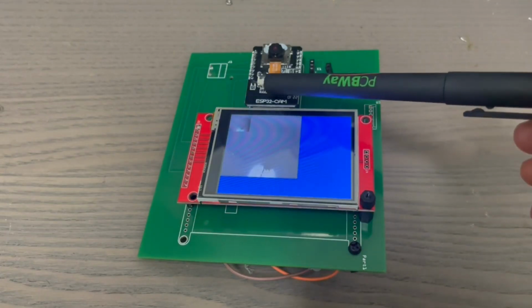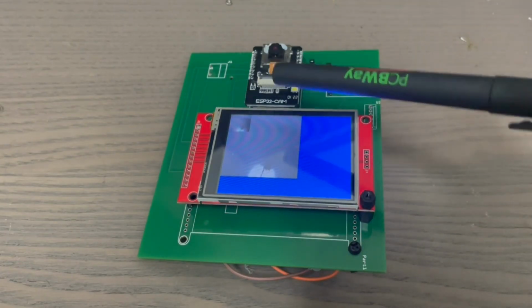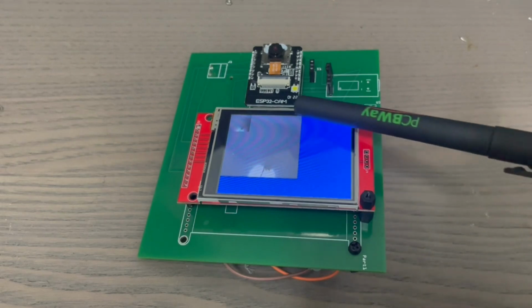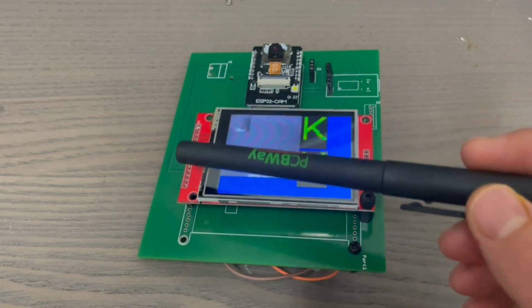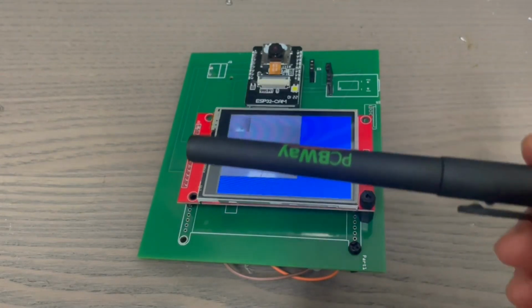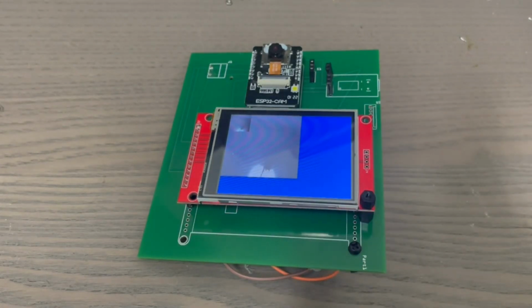I've uploaded the code to the ESP32, and the hand needs to be positioned fairly precisely in front of the camera, which is why I've done the extra work to include this TFT in the project, so I can see where the hand is, I can see what the camera's seeing. And so basically the user has 5 seconds to position their hands, and then the code makes the inference about what letter is being shown by their hand, and displays 2 letters with the highest confidence.